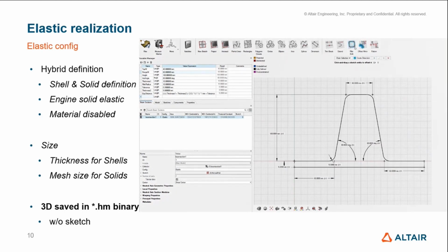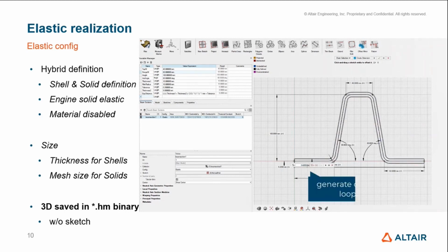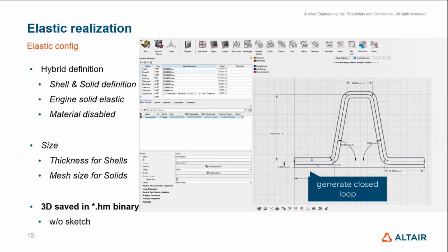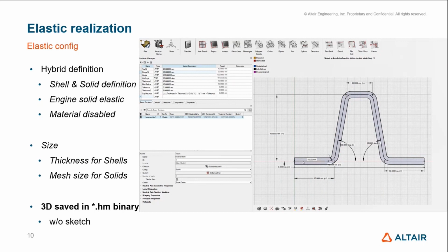Now by entering the edit mode in Sketch, we can actually select one line and do an offset, which will turn a linear domain into a solid here, basically, with this offset of 5. And since it's a hybrid definition, I have to make sure that the original line will be removed. So now we change it to a construction line, so you won't have any duplicate domain at this location.